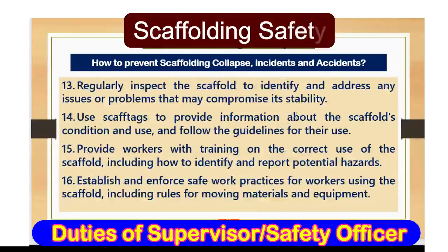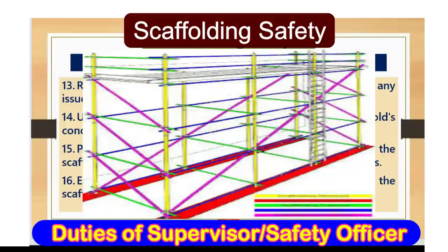Number 13, regularly inspect the scaffold to identify and address any issues or problems that may compromise its stability. Number 14, use scaff tags to provide information about the scaffold's conditions and use, and follow the guidelines for their use. Number 15, provide workers with training on the correct use of the scaffold, including how to identify and report